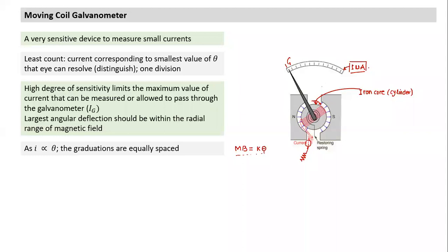Okay, and that's all you can fill up. That's the only key point here. So the moment I think of a moving coil galvanometer, this is the point that should come to mind. There's a torque which is trying to rotate, and there's a torque which is trying to resist angular displacement. When both become equal, now we can fill up this value. What is M equal to? NIA. So NIAB is equal to K theta.